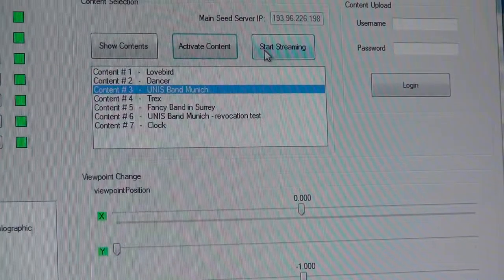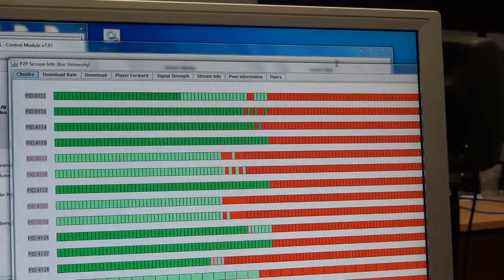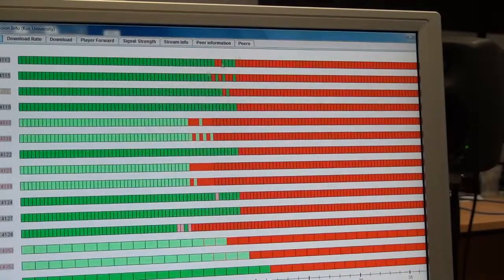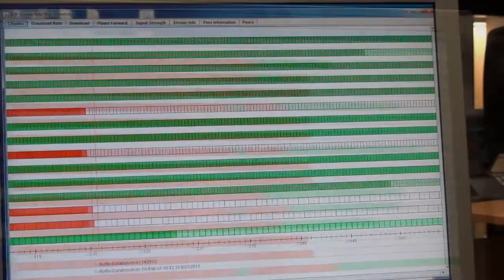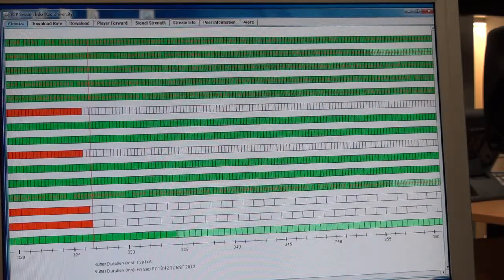And in the third step, the DVB-T receiver is activated and starts buffering the incoming DVB-T streams. After the activation, the peer-to-peer engine is immediately updated with the current DVB-T clock and calculates the next chunks to download accordingly. The long red lines on the screen denote the skipped chunks in order to catch the DVB-T stream from the correct position.